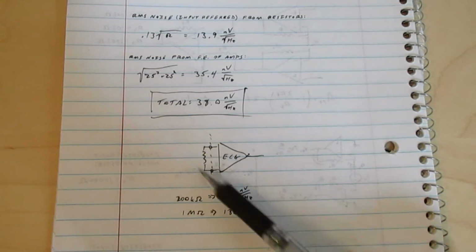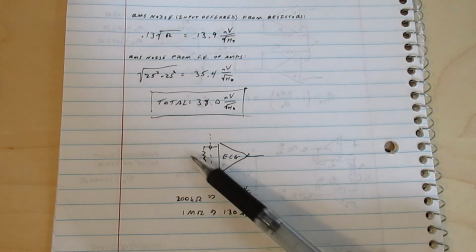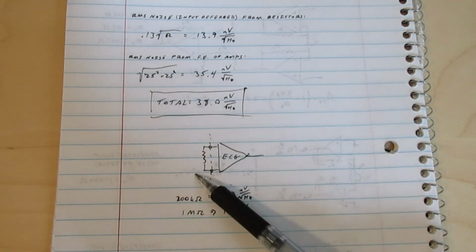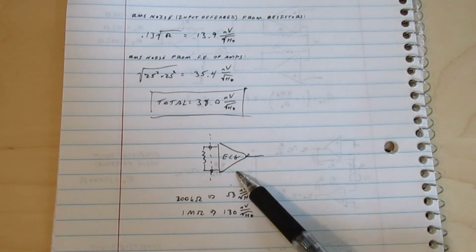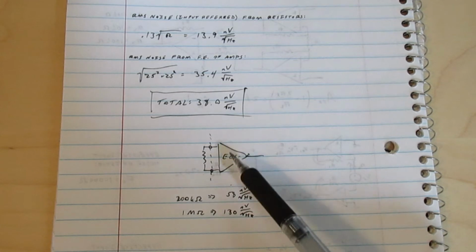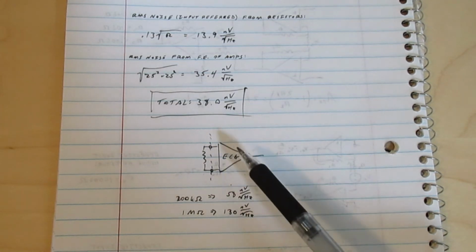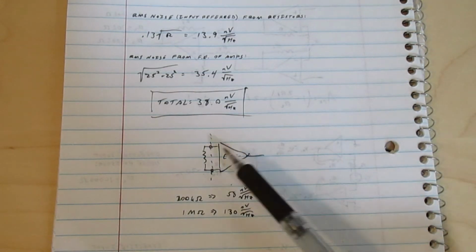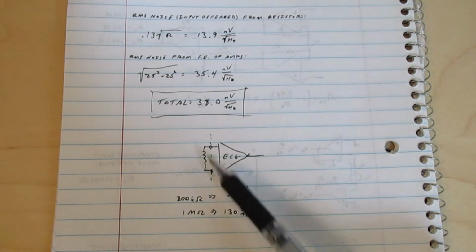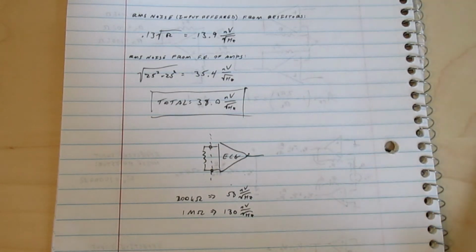First of all, I learned that the noise performance of my ECG is almost entirely dominated by the thermal noise of my body that's going into the circuit. It does not mean that all the math I did was for nothing, because now I know for sure that I don't have to waste my time improving the thermal noise of my ECG circuit, because even if I did, it wouldn't make that much difference anyway. Also, I know that the conductive jelly will probably help, since that will reduce the contact resistance at the electrodes and reduce thermal noise that way.